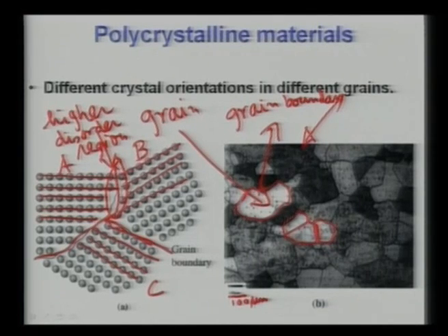However, we should also notice here that this grain size is not a fixed value. There is a variation of grain size across this microstructure. So a term called grain size distribution is often used to characterize the microstructure. In other words, you can say roughly from the visual look of this microstructure that grain size here typically varies between 50 to 150 micron. And if you say that, then you will be completing the description of this kind of microstructure. So this is in general a brief on how the microstructure looks and how one can characterize it in scientific terms.